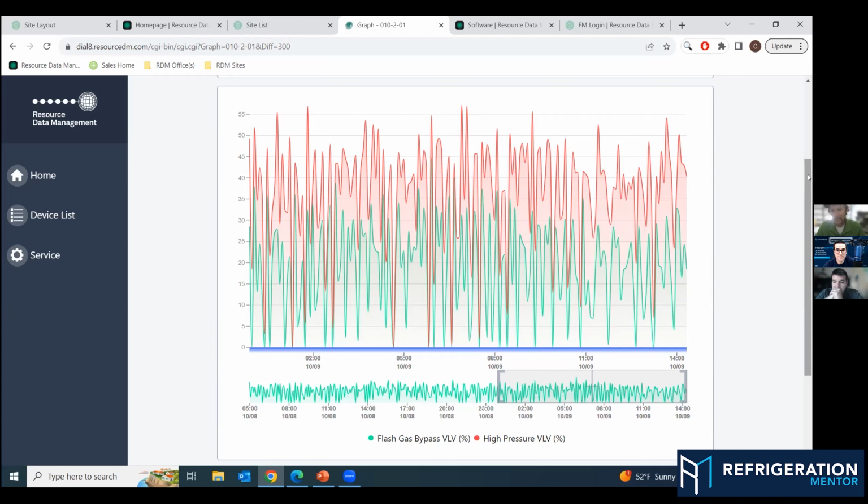So like I said, this store is going to need to be, in my opinion, looked at. But right now, it's running okay. The placement of the sensors is so important. Then you've got to think about the fan staging. Are the fans banging on, ramping up or ramping down? Yeah, we had that problem at this store.